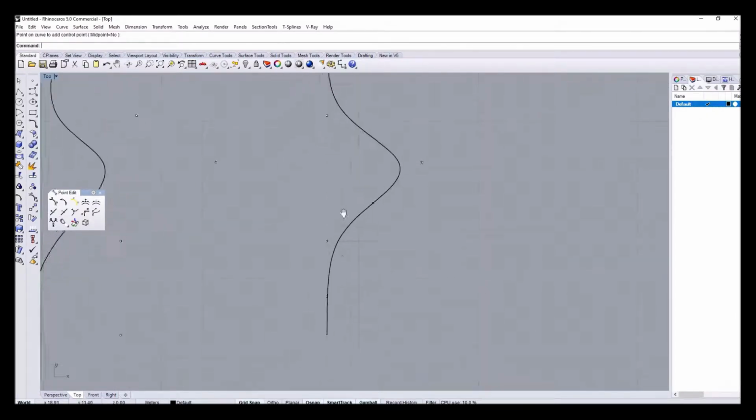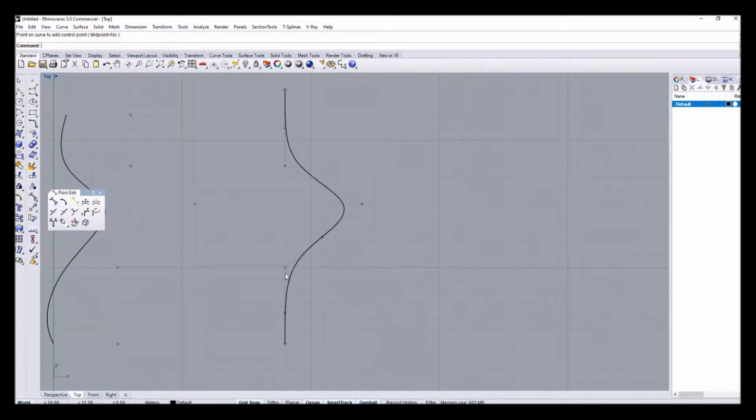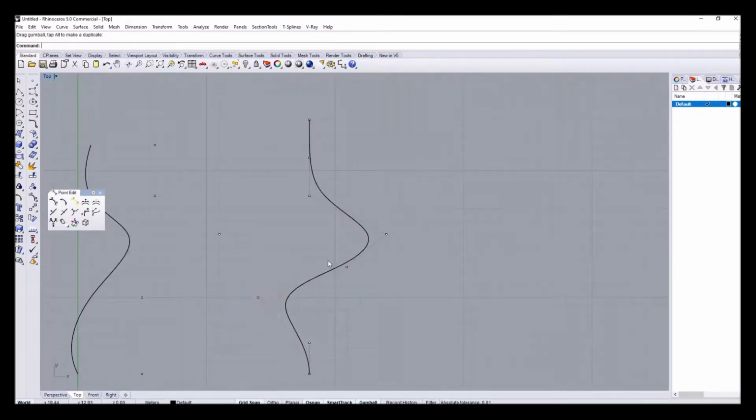A quick tip: all modeling of curves essentially starts with a simple curve and adding more control points as we go. We can, for instance, now move it towards the left, and now I have two movements, one towards the left and one towards the right, as much as adding control points. We can also subtract them. I can remove control points by selecting the curve, and the points that are going to be removed will be highlighted, so if I click on that, it will be removed.